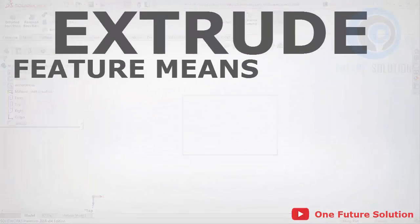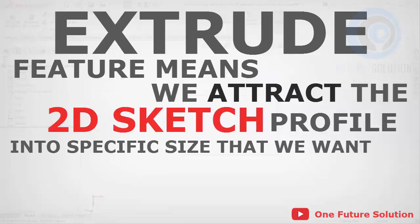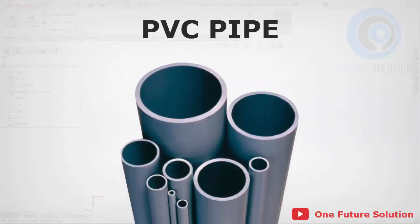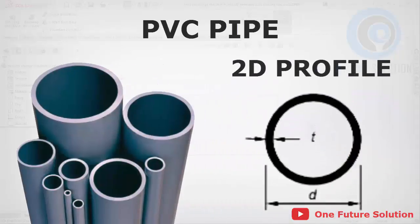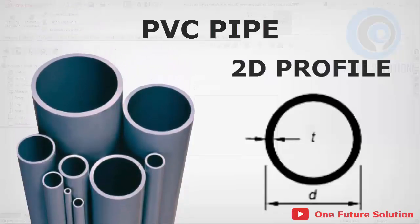Extrude feature means we extract the 2D sketch profile into a specific size that we want as a 3D extruded geometry. Like the PVC pipe as the sample. The PVC pipe has a hollow circular as the main 2D profile, and then the main 2D profile is extruded into a specific length. So we can get the 3D geometry of PVC pipes through the extrusion process.